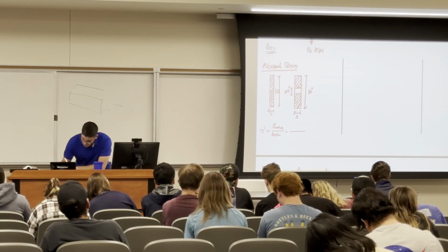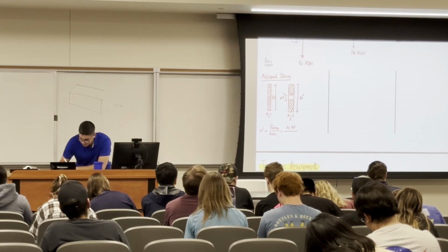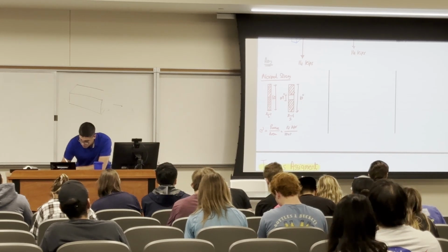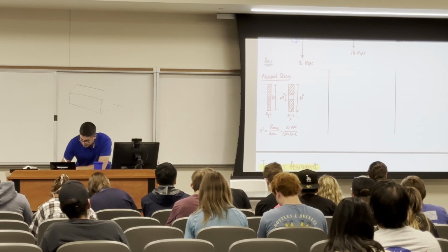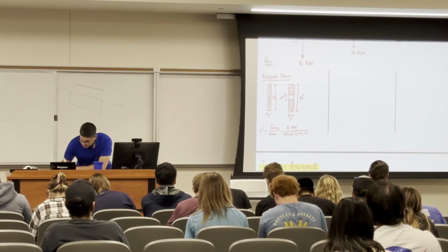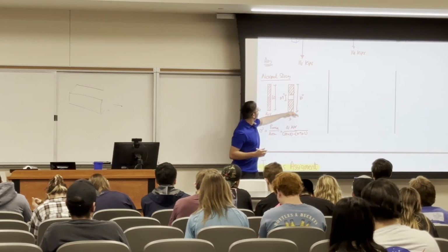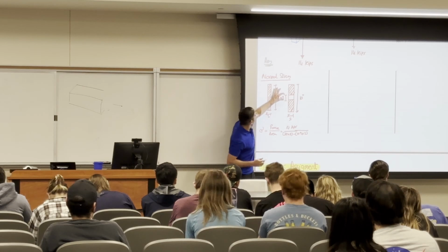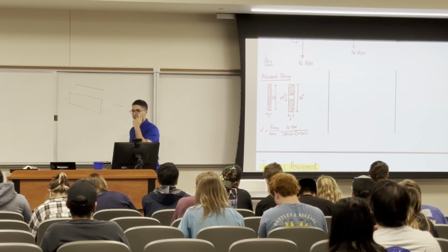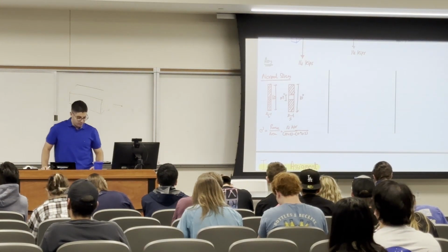Remember that. So the force is 14 kips, and kips is kilopounds, over the area, which is 10 times 2 minus 0.9 times 2. Ten minus 2, like the whole thing, I'm subtracting from it 0.9, which is the diameter, times 2, which is the thickness. You all following? Any questions? Okay, what's the answer for this?